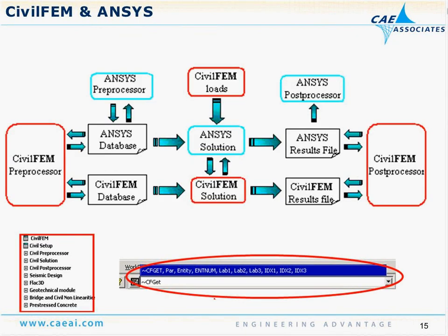The way ANSYS and CivilFEM are integrated is that ANSYS is command-driven software. CivilFEM is also command-driven software. The difference is that the CivilFEM commands start with the tilde character, to differentiate them from the ANSYS commands. There is no restriction in terms of how you integrate ANSYS and CivilFEM. So you can have a whole series of ANSYS commands integrated with your CivilFEM commands. You can use ANSYS features that may not be directly supported in terms of code checking, for example, but can still be used in the model for simulation.